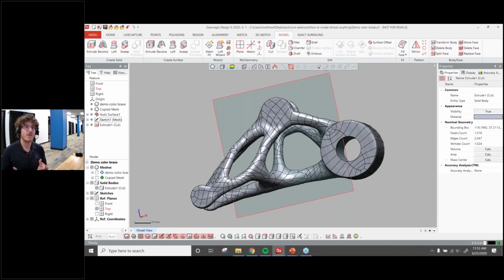We did that very similarly with that demo block file where it was something that we already had pretty much modeled, but we had this one surface area that we needed to be hand carved. We're able to turn that into a mesh, that mesh into a surface, and then apply it to our solid body. So this is just a brief little introduction into the idea of hybrid modeling, but as you can see, it applies a lot of the same rules that Sean was just showing, which is using some extra surfacing tools and the ability to just take one-to-one references from the mesh. So that was just my section I wanted to go over.